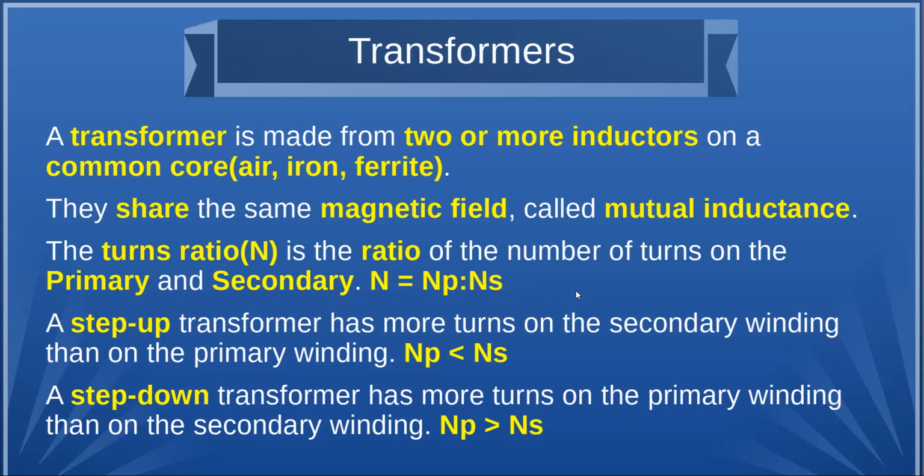If you had a one-to-one transformer, which you were just using for isolation, and a lot of times you'll see that in AC utility power used to isolate grounds, it'll have a one-to-one turns ratio. So the same number of windings on both sides. There's no voltage increase or decrease.